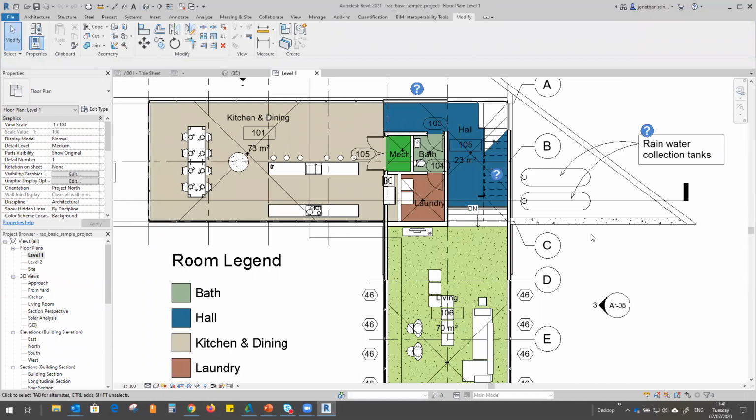And I suppose the first thing is, I like to keep as few wall types as is practical to the project. So that's going to depend on the size of your project and how many walls you need to create, and you'll need to make that call. A general rule I like to work to, if you don't necessarily have to model every single finish. So for example, if it's a tile finish in the bathroom and a tile finish around the kitchen counter, that can be simply notated on your drawings.